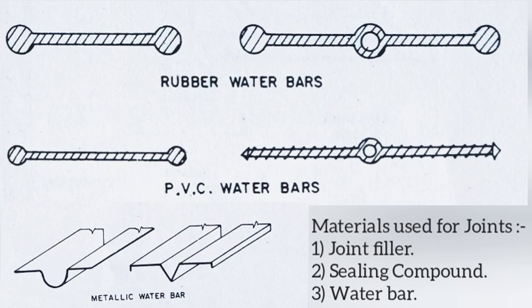The function of the sealing compound in a joint is to seal the joint against passing of moisture and to prevent the ingress of dust, grease, or other foreign matter into the joint. It should be insoluble, non-toxic, and tintless and should be readily workable for placement in position. Mastic or hot applied bituminous sealing compound is commonly used for this purpose.